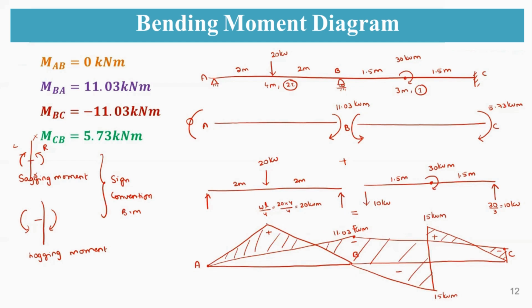So suppose if you want it at this loading condition, the bending moment value will be equal to the total ordinate of this, that is 20. So 20 minus this ordinate is going to give the shaded portion value. So that will be your net bending moment. So this is your final bending moment diagram. I hope you are able to understand this.